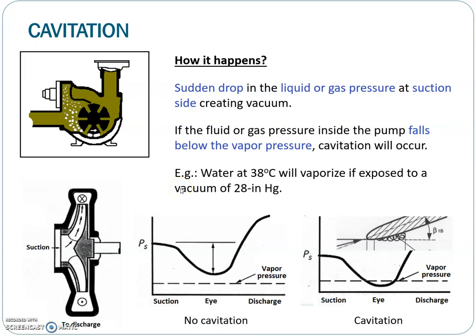In classic cavitation, bubbles form at the impeller eye due to the pressure drop caused by friction or velocity. The bubbles are swept outward along the impeller, causing a change in liquid velocity, which results in the bubbles collapsing. Implosions of the bubbles, or random noises, cause small wear on the impeller surface.